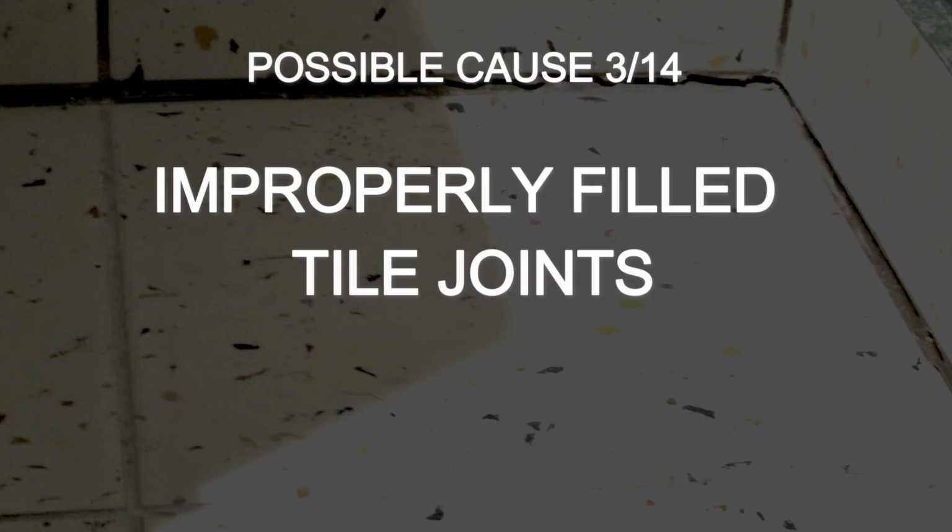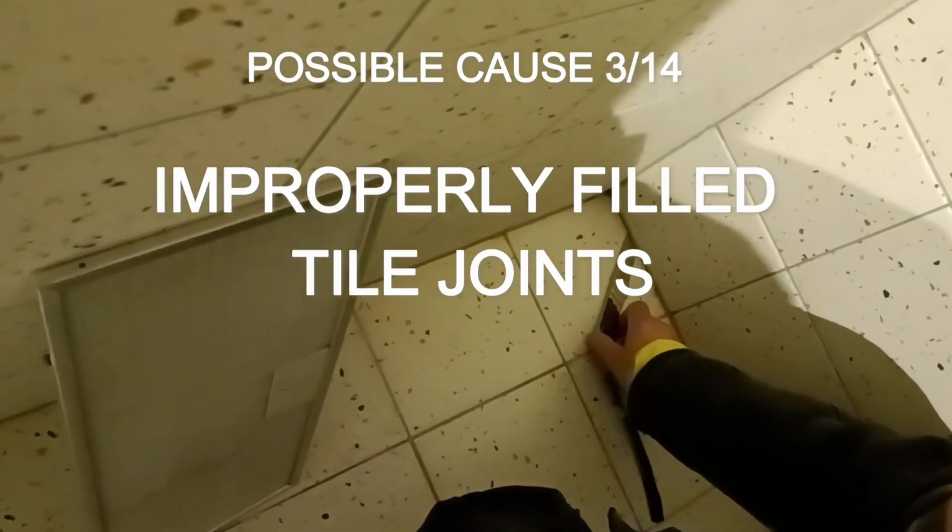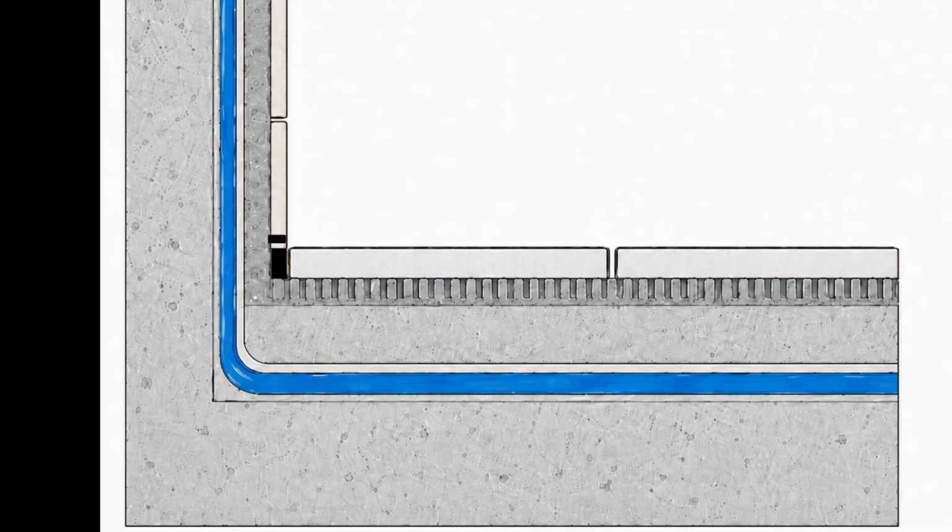The third version was obvious during the very first inspection. In many places, the joints were cracked or not completely filled. A knife blade could fit into some of the gaps. The tile covering and its joints are the first waterproofing barrier. Water can get under the tiles through leaky joints.